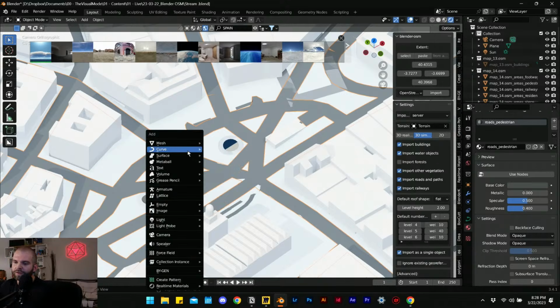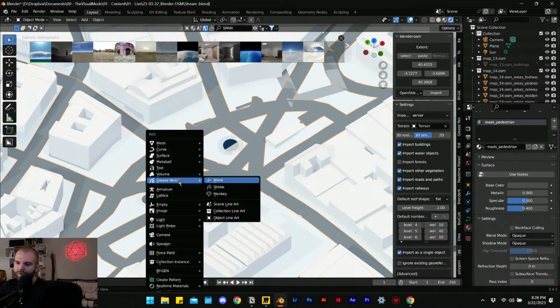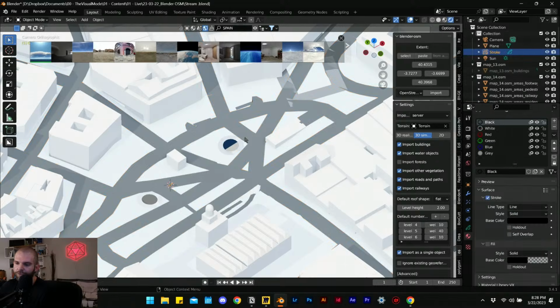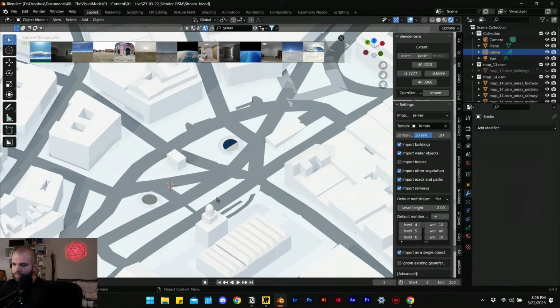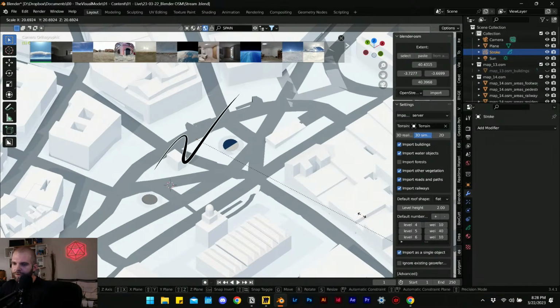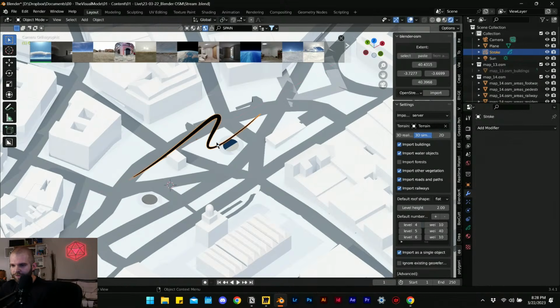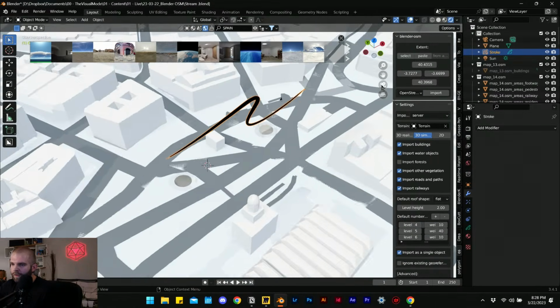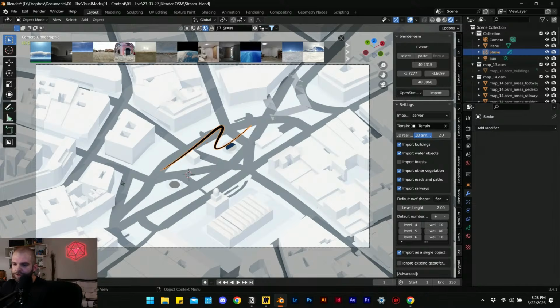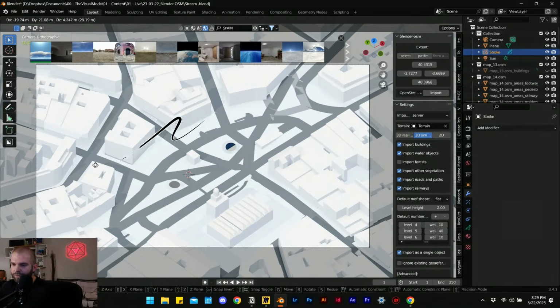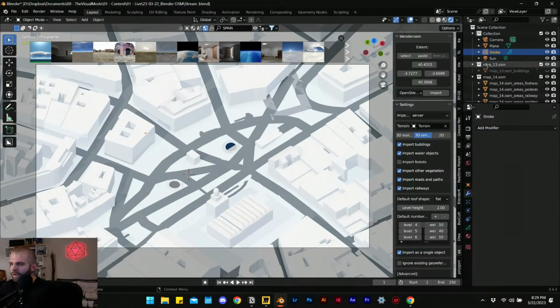What really can make an impact at the moment is adding a grease pencil object. So we'll add a grease pencil stroke. And what that does is, go over to our modifiers here. If I were to enlarge this, it's just a line. It almost looks like a 2D stroke of a line, but it's a 3D object here in the scene. And what we can do is project this line all over the objects that we're looking at here. So if we take this over to the side, or make it small so we don't notice it, we want to keep it handy over here in our scene collection so we can refer back to it.